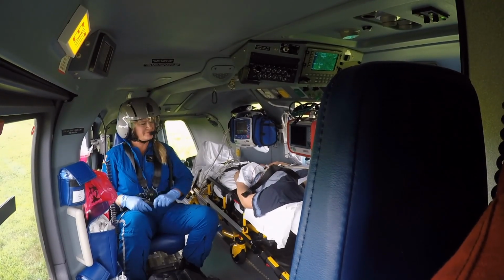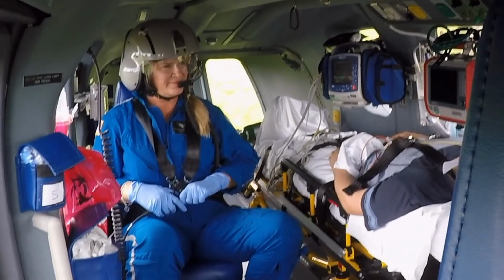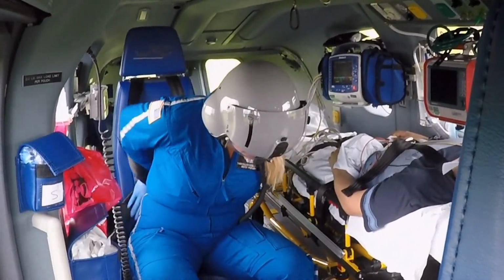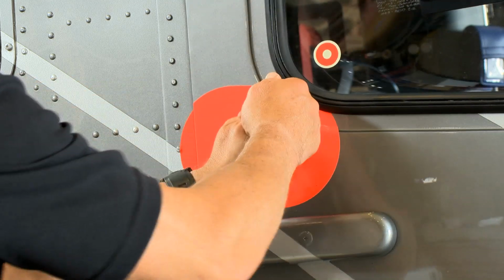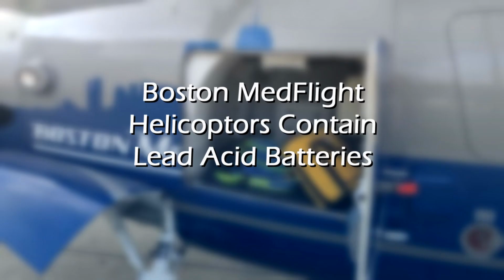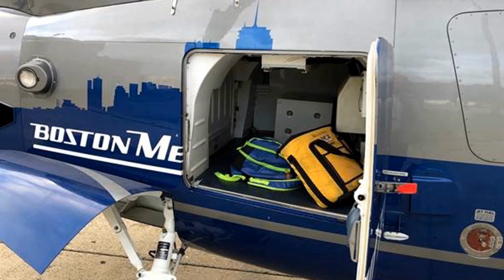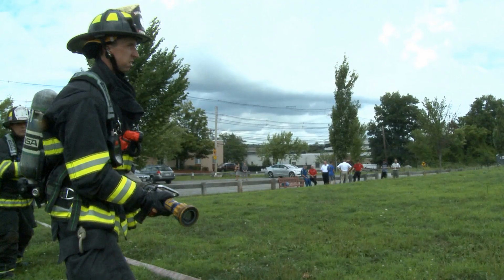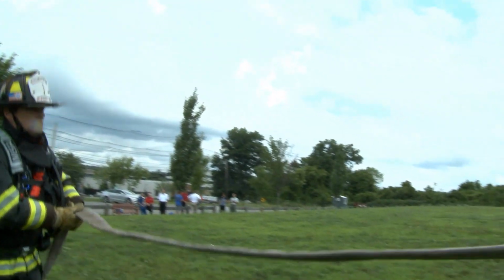If a crew member needs to be extricated, seatbelt systems are unlocked with a quarter turn of the buckle in either direction or cut away with a sharp knife. All fire rescue personnel should be familiar with operating helicopter doors to aid in extrication of crew members. Boston MedFlight helicopters use lead-acid batteries located on the left side of the baggage compartment of the S-76 helicopter and behind the engines of the H-145 helicopter. Follow these guidelines in the event of a helicopter crash.